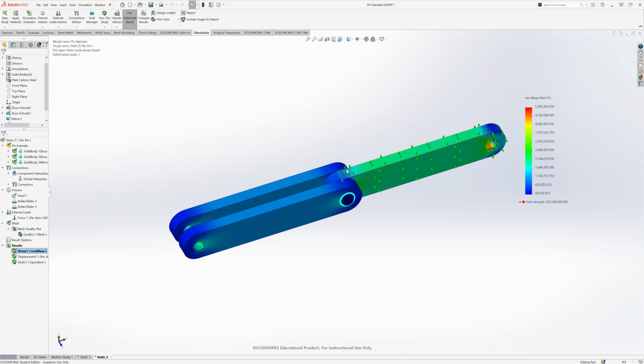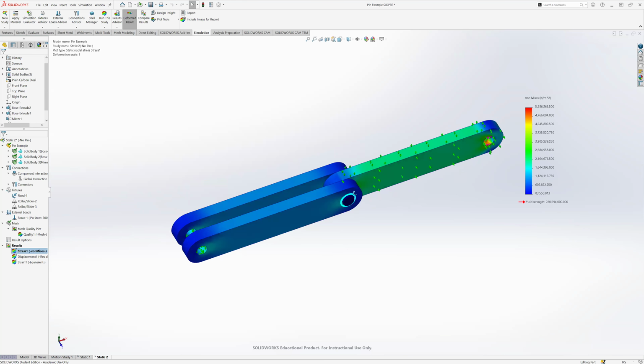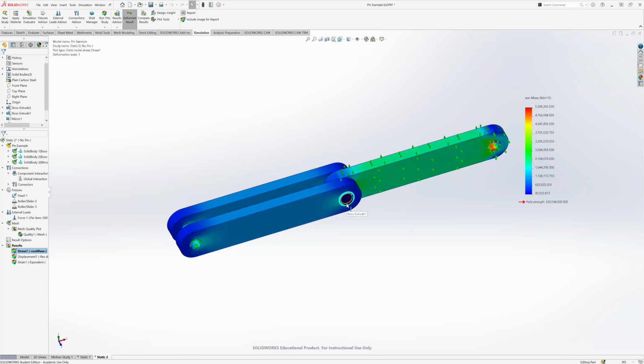Maybe you set up your fixtures, you think, correctly, and the behavior looks correct, but maybe the fixtures or the forces you set up are not giving you realistic stresses on different components, although the behavior looks correct. By running a quick calculation by hand, maybe on the stress of the pin or something like that, if you're doing it obviously not as a connections problem, it's a really easy check to figure out, okay, let's see what we're dealing with here.